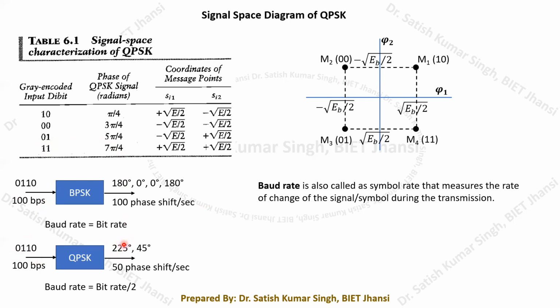So that will be the phase change in the carrier that we can observe corresponding to 0-1. Similarly, corresponding to the 1-0 di-bit, this value should be pi by 4. So you can write this as equal to 45 degrees. So these are the 2 phase changes that we are going to observe in the case of the QPSK system as compared to your BPSK system.